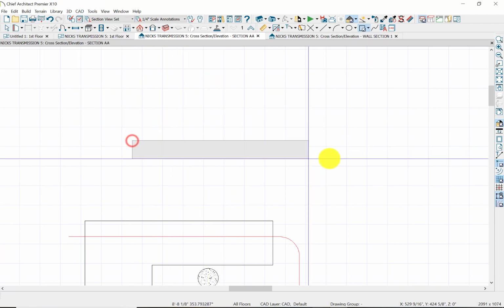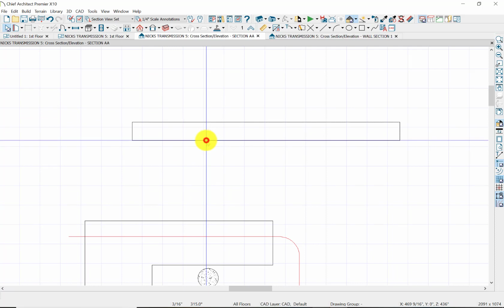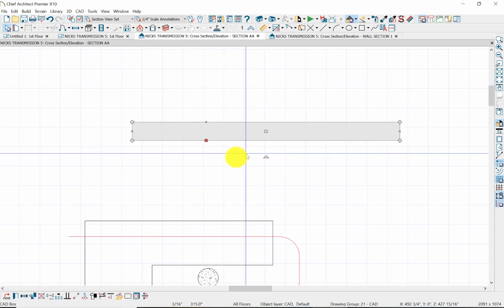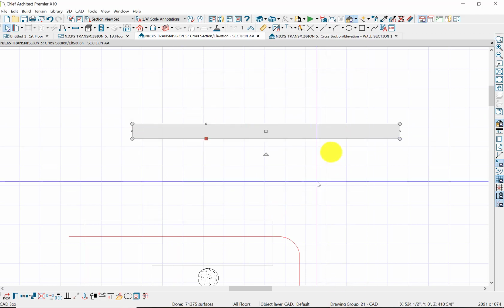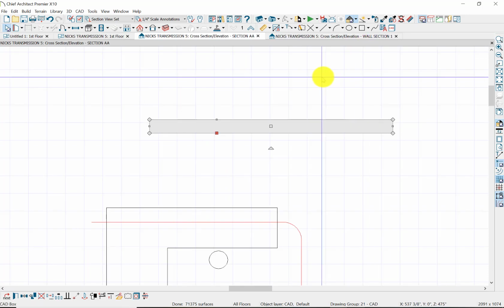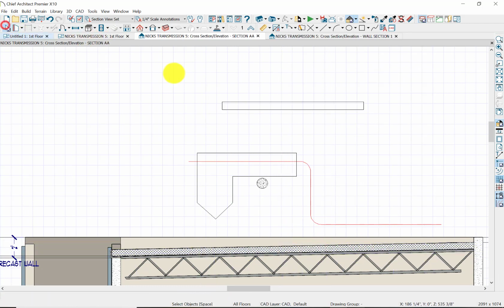Box is great because instead of a rectangular polyline, it keeps it locked in at 90 degrees, which makes it great for framing members, pseudo framing members, for detailing in. Let's say it's a 2x10. Say the height of the 2x10, 9.25, which is your actual dimension of a 2x10. So now that signifies a 2x10, and let's say it has a slope, and it has to match this pitch, which is a 1/4 inch per foot. 2x10 is slope and 1/4 inch per foot.